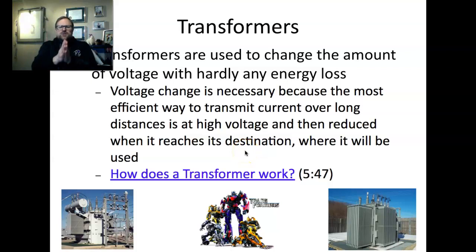So, imagine this scenario. You've got a generator somewhere. Let's say that generator is actually hooked up to a big hydroelectric dam. And so you've got water flowing over these turbines. These turbines are spinning as the water goes over, right? And those turbines are attached to an armature, which has a coil sitting inside a big magnet. Well, I've just described a generator. As this spins, the coil spins inside the magnet, and as it spins, we're generating electricity in that coil.